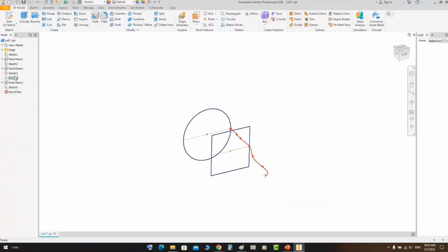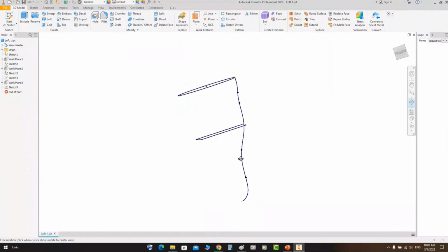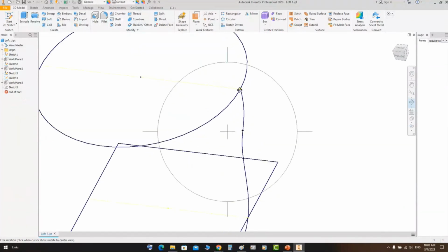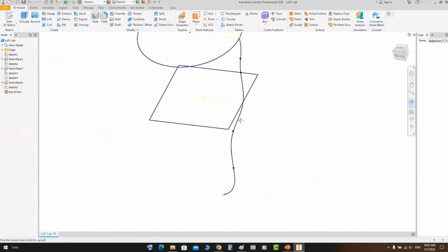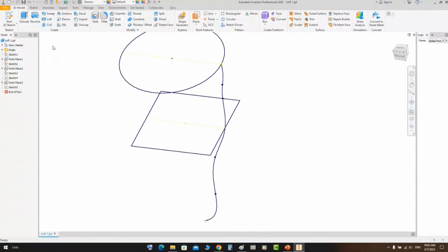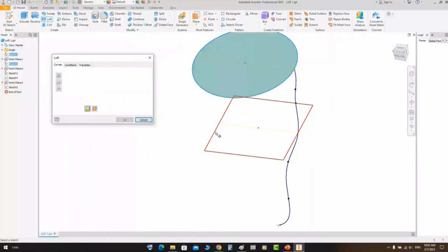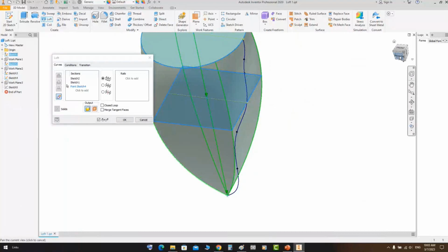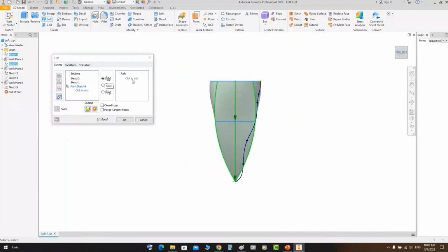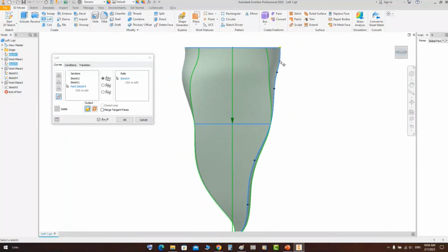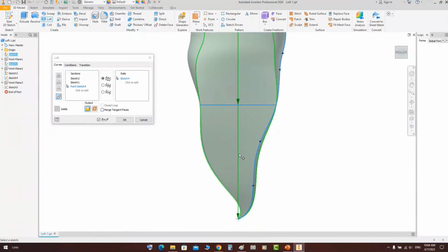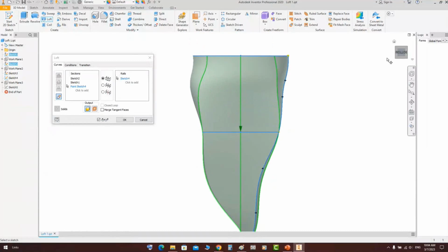you can make it with a controlled guide at the outside. If we make this outside sketch, which connects the three sketches from the outside, you can use it as a guide. So from here, you can make a Loft and connect between those shapes like that. But in that way, here we will select rails, a guide rail. When you select this rail, you can see that you change the configuration. You make this surface railed to that guide, and you can add more guides on each surface.